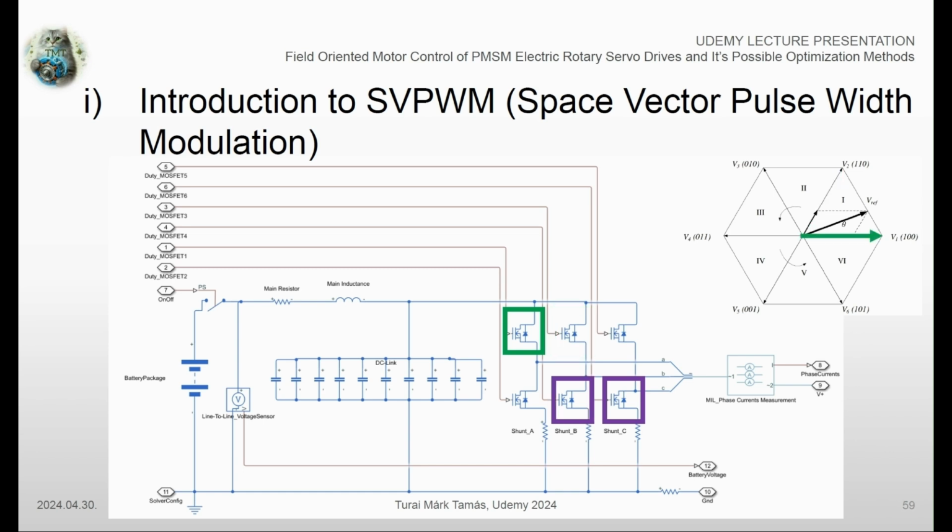An average 30 degree output voltage vector is being modulated in this case, hence we are changing state between the V1 and V2 base vectors, giving the same amount of time to be taken for the MOSFETs when we are switching between these two states.